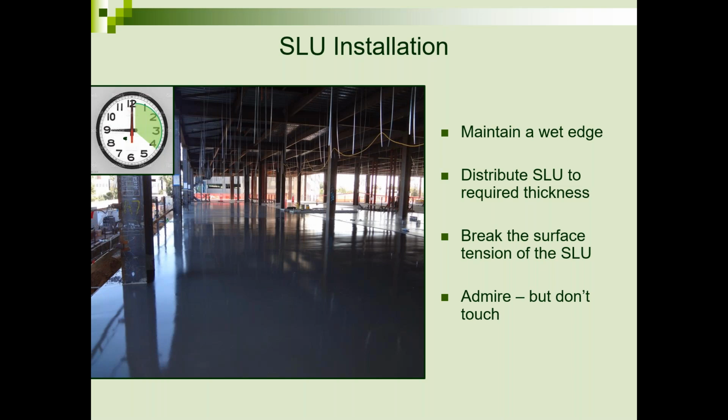The product that's closer to the foreground, maybe that's still workable, but understand your working time. Don't eat up your working time by excessive mixing. If it's a hot, windy day, low humidity, whatever, your working time is going to be affected. So understand what it is, so you don't get cut short. But after the working time, all you're doing is looking at the great job you did. If you have to correct the surface, it's done after this product hardens and you can get on it. Trying to correct the defect in the installation after the working time creates more problems.